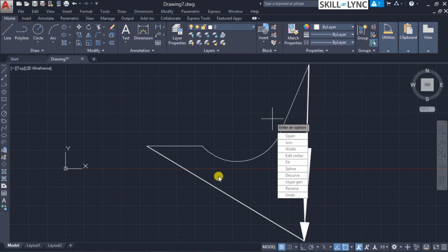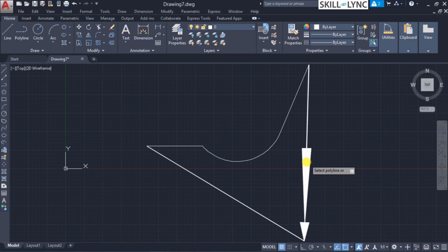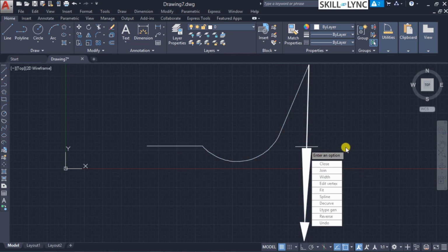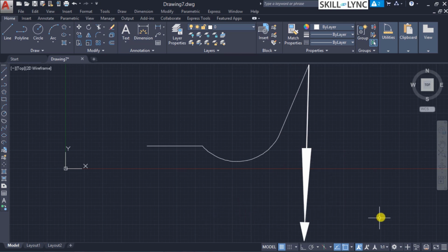So right now you can see that it doesn't operate because first you have to make this polyline to be an open one. Second, let's see what is the variant of it. So towards that, let us just make this as open. So now we are selecting the single polyline and making it open. So this is done. So now let us consider that we have a single line segment that goes approximately here. So it is something like this. Okay. So in this case, now the objective is to join this line segment to this polyline and vice versa, and then convert it to be a single object.